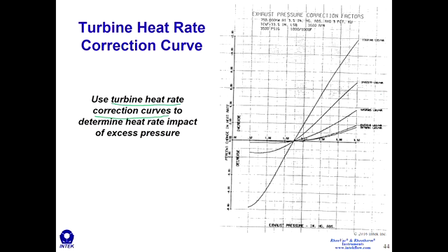And so how you use this graph is you choose the main steam flow. You could create a surface to fit all of this data, which is what we do for more complex analysis, or you can pick a curve or draw a curve in for a fixed duty and do analysis on filtered data for fixed duty. But what you do is you pick your curve here, and you plot your measured pressure at this star here.